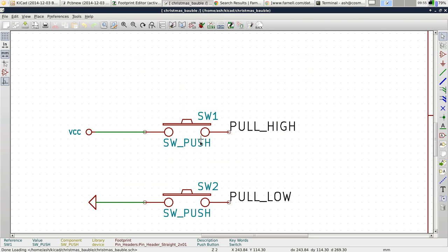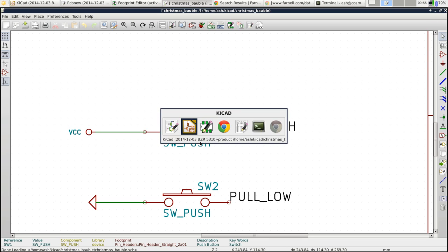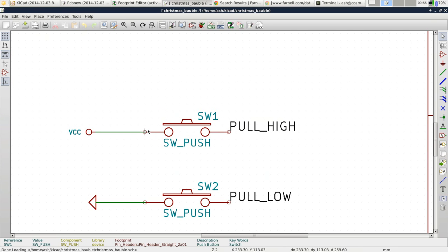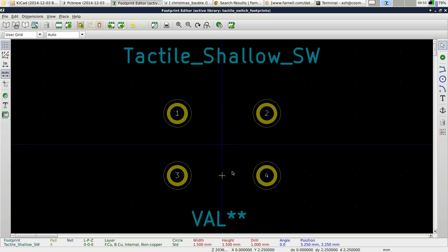We could put 4 pins on there if we wanted, because maybe there's some circumstances where you're going to use all 4 of these pins, whereas really, in a way this switch is just like this because it needs 4 anchor points essentially. But this can be a little bit annoying because we've labelled the pins 1, 2, 3 and 4, these will be mapped to pins 1 and 2, and then there'll be 2 pins left where it doesn't know what to map them to.